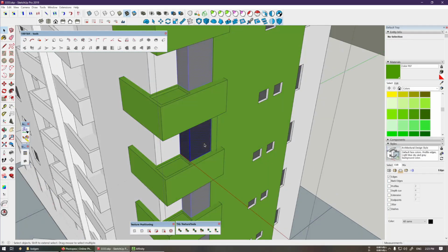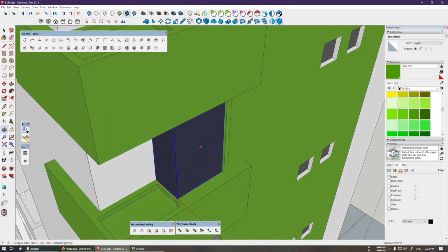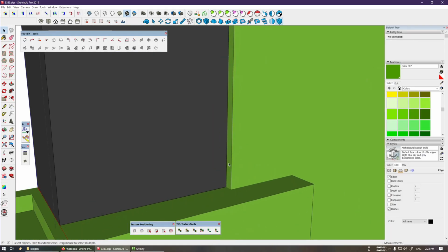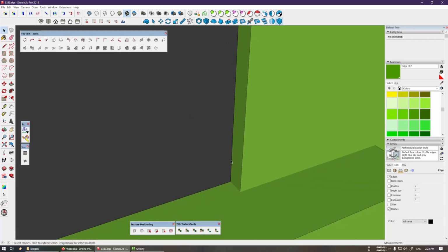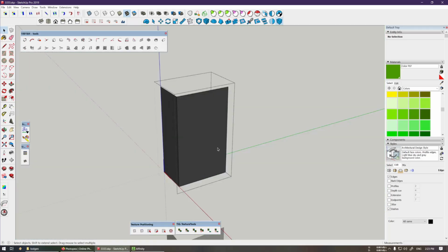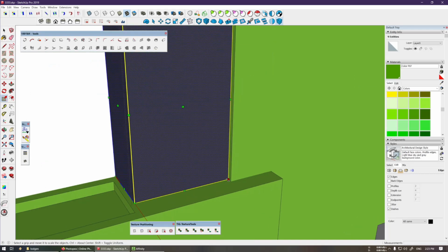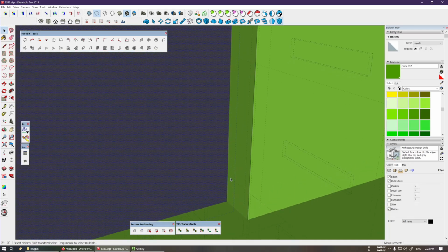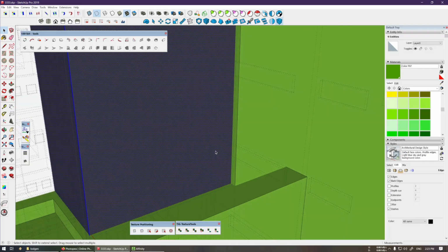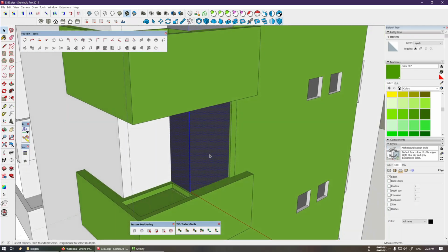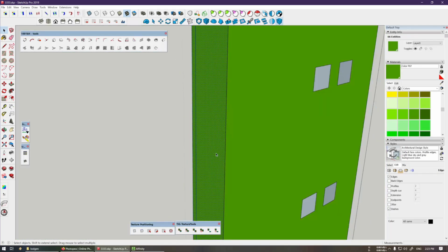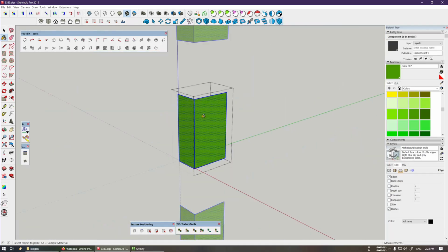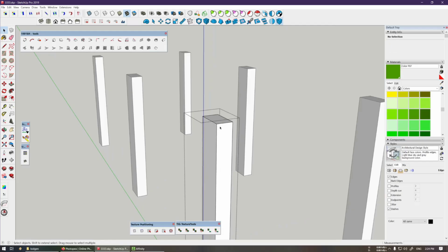Anything else? Okay, let's say this window. Okay, this window has an inner face that we do not want. Delete that. And the line is touching the face on the other group. You do not want that. Scale it up a little bit, so the line is clipping through the other groups. This will avoid cutting the surface into multiple smaller geometry. Okay, this is optimized.